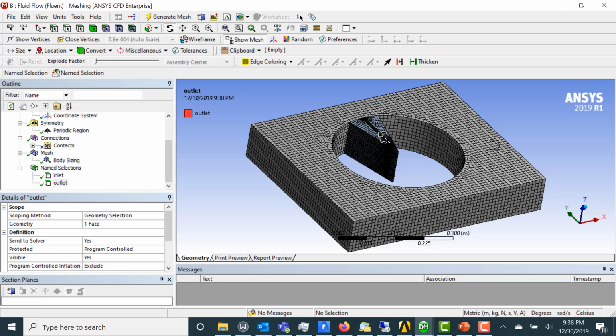We're going to be setting this up in Fluent as a mixing plane problem, and mixing plane problems are very powerful because you can get a steady state solution where you're only modeling a periodic section of a rotating turbomachinery component without having to model all, in this example, 12 blades all the way around. Here we're modeling only one of the blades, so you reduce the meshing requirements. The computational bandwidth is substantially diminished.